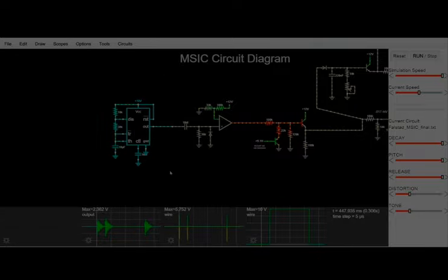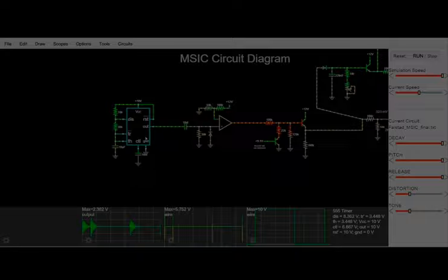this block is the sequencer block. As you can see, you might have identified that this is a timer IC. The sequencer generates periodic gate pulses that define the rhythm of the kick drum. This section mainly consists of a timer IC in astable multivibrator mode, and the frequency of the signal is adjusted by a 50K potentiometer, which we have used in our main circuit on the breadboard implementation. And this allows us to vary the frequency from 2 Hz to 6 Hz.